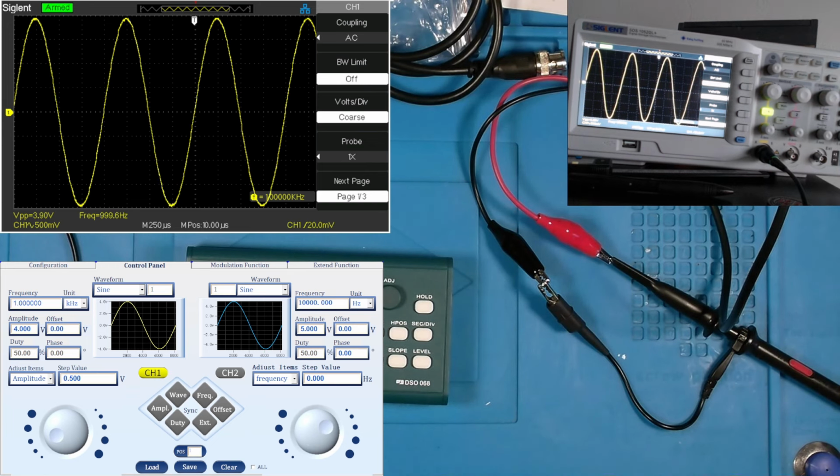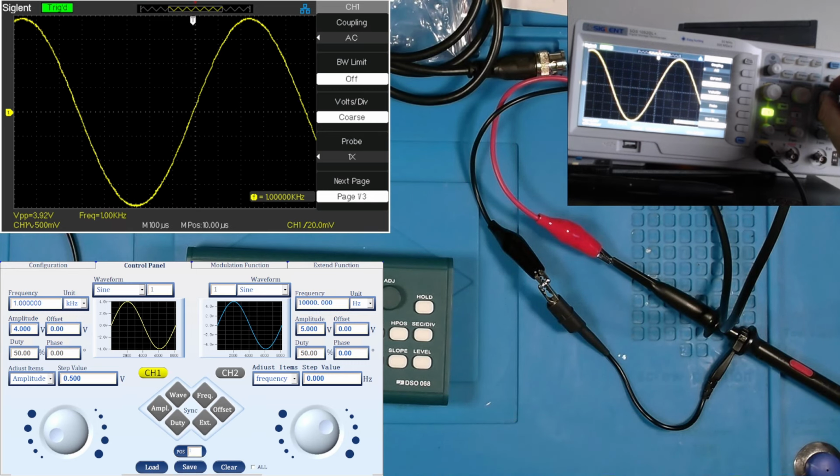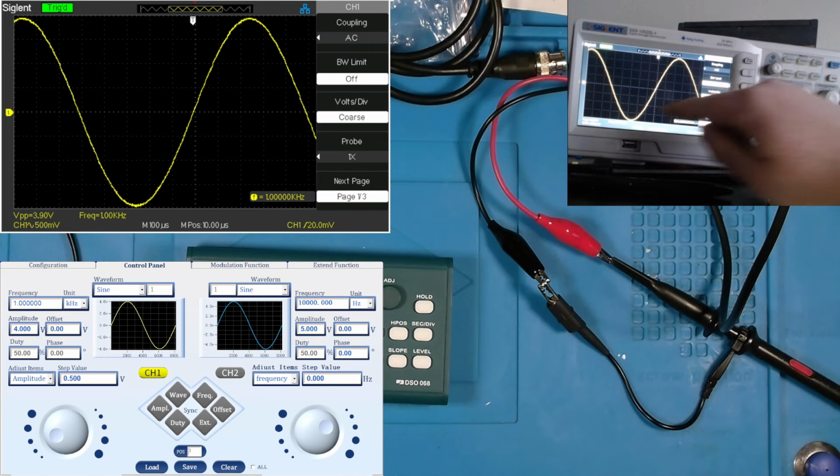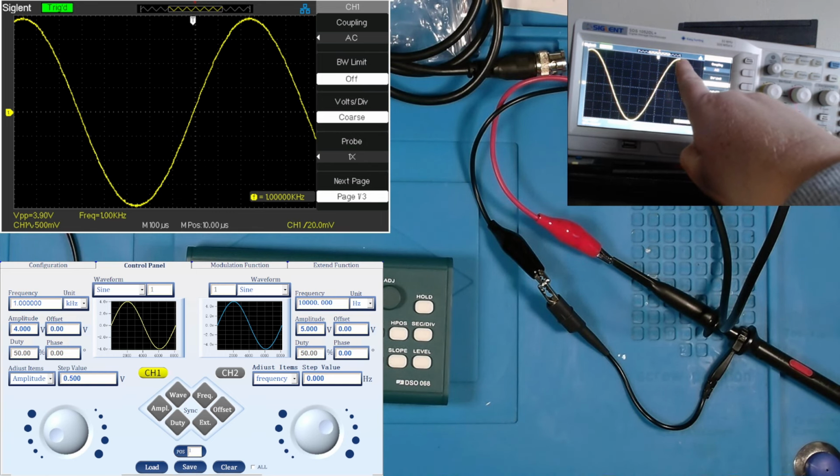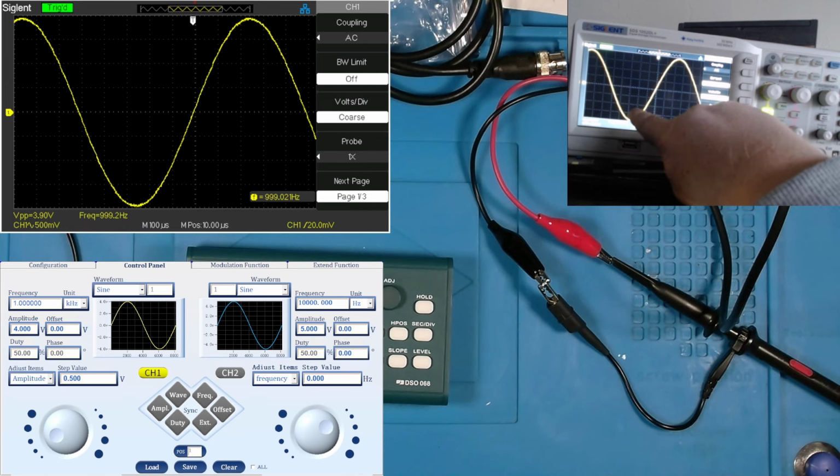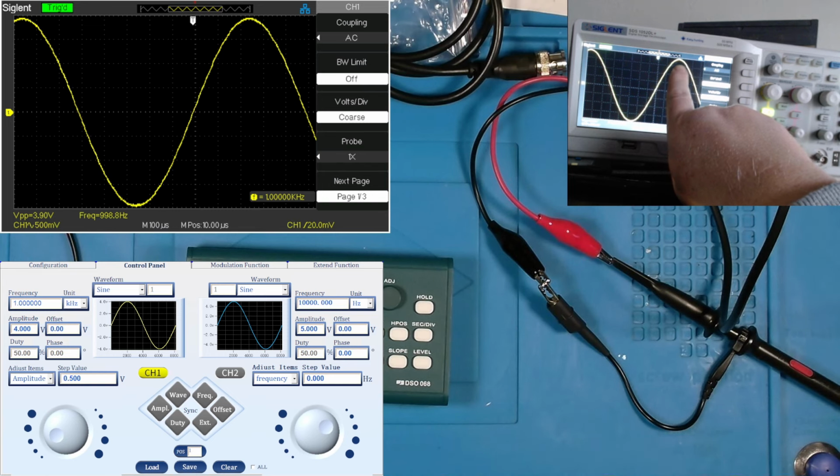Now, when I'm physically looking at my waveform, there are some things I'm actually checking out. You often hear me say, well, that's a nice sinusoidal waveform. So I am looking from peak to peak, and I'm making sure that there is no dips or distortion or any indication that the waveform itself is askew. Okay? No cutoff in the frequency, nothing like that.